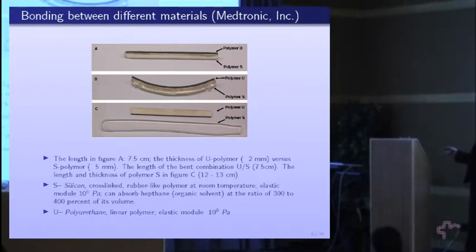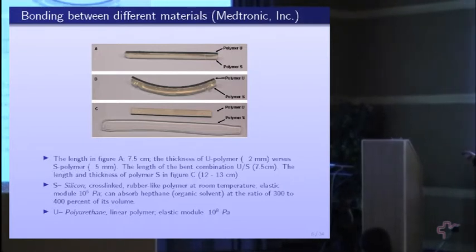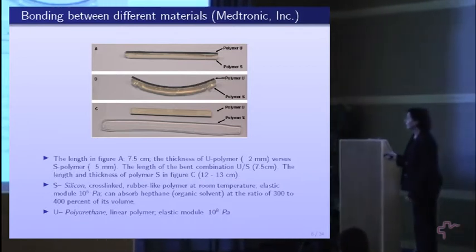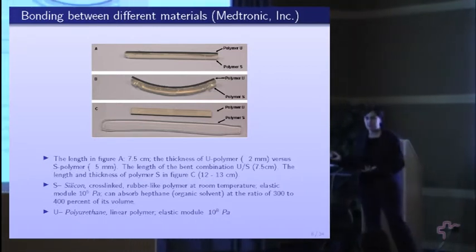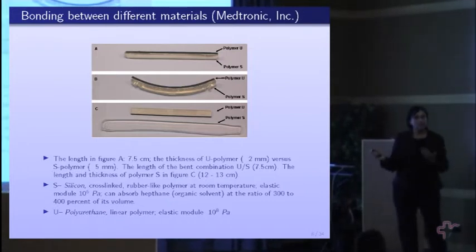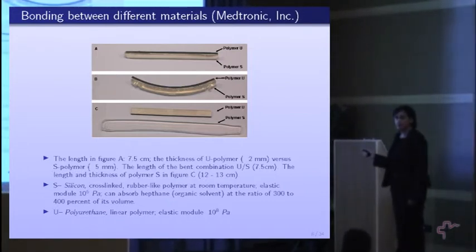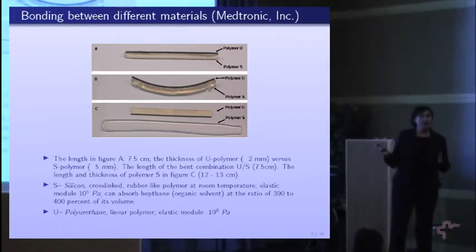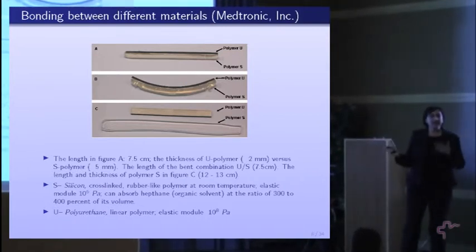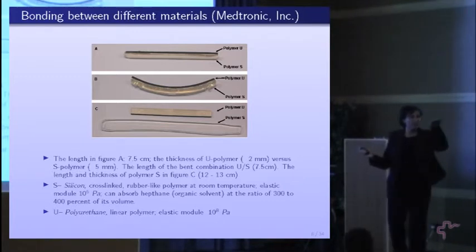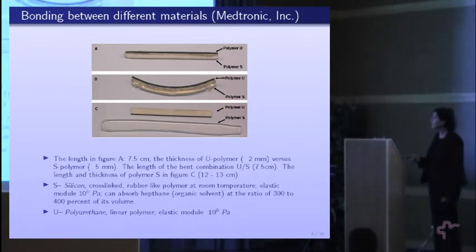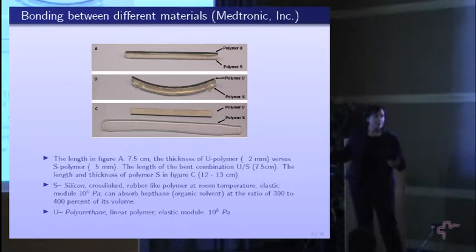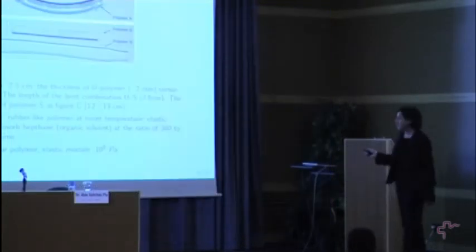We see that the bottom one swells a lot more than the top one. However, when the stresses at the interface are too big, this is what happens: they fall apart, because one swells very little and the other one swells a lot. One of the main issues is that this is not a static problem. If we calculate the stress at equilibrium and then the stress at the interface, this is going to give us only some estimate of the build-up stress. But this is really a dynamical process, and the stress can peak after 10 years. So the question is how this behaves in 20 years, which is what the industry computes as the time that we would like the device to last.